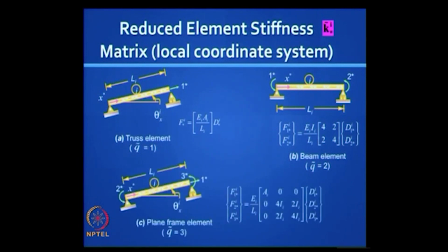It's nothing but the truss element and the beam element put together, and we assume that the axial stiffness is independent. We ignore any axial flexure interaction. That's what we do in first order analysis. We will study later in the 7th module, there is an interaction because it behaves like a beam column. Right now we pretend there is no interaction.